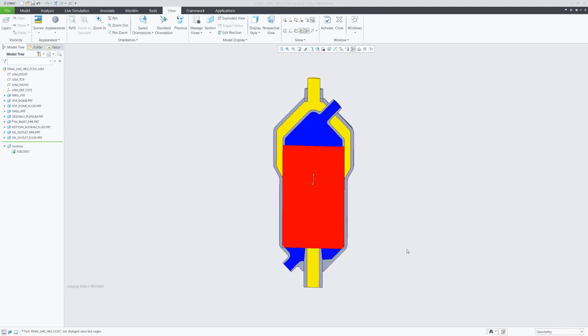The next aspect about the plenums is they generally follow the contour of our shell. So when we get to generating the shape of the shell volume, seen here in gray, not only do we need to take into account DFAM, but how we might want our flow to be distributed into the hex core.